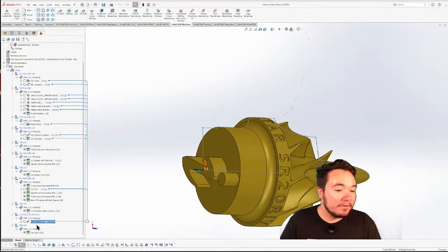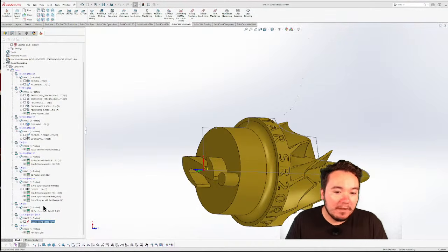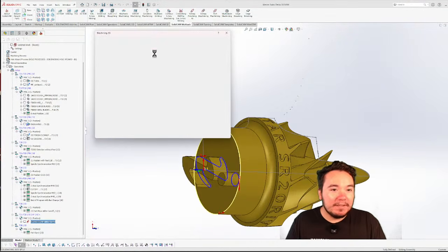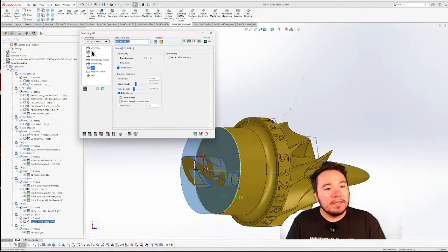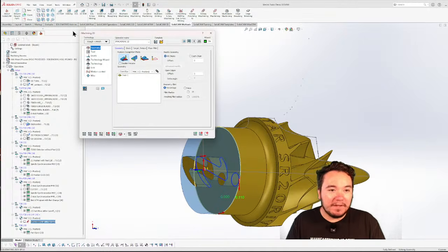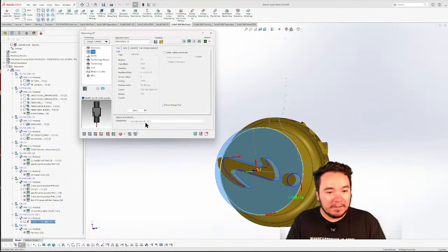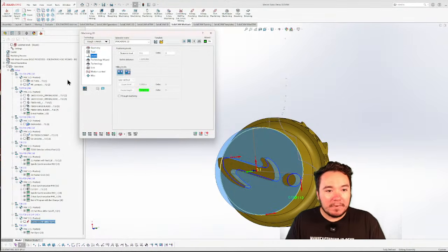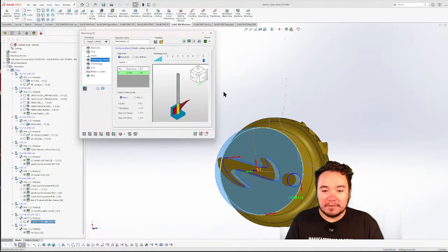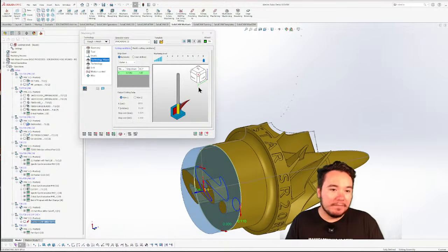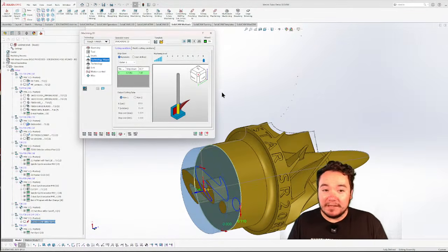All right, so our iMachining. iMachining was super easy. Let's see. It looks like, yep, I just selected the face. Made sure it's Rough and Finish because I do want to finish it. Grab my tool. Levels are automatically selected because we're using automatically updated stock. We're running it at level 8. You'll see it at the show.